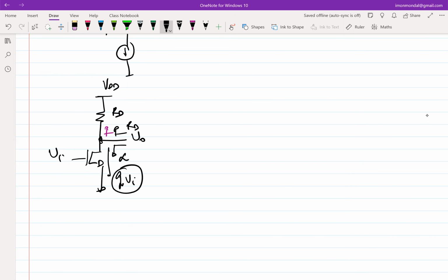But I saw some head scratching, because how do I put a transistor there, right? Whose drain is at the bottom side, because drain is supposed to be at the higher voltage. So essentially what I'm saying is, can I do this? A transistor's terminals are not decided, right? Geometrically or physically, it's a symmetric device.